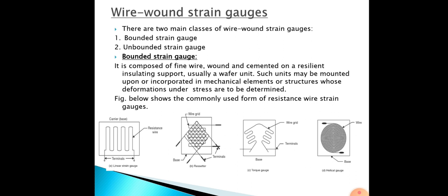So when displacement takes place between the attached points M and N, meaning there is movement, either stretching or compressing, you will get the reading of the strain on a graduated scale. On the graduated scale you can see in the diagram that the pointer will be moving, and accordingly you will get the reading.